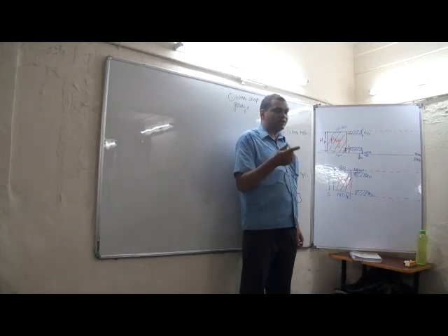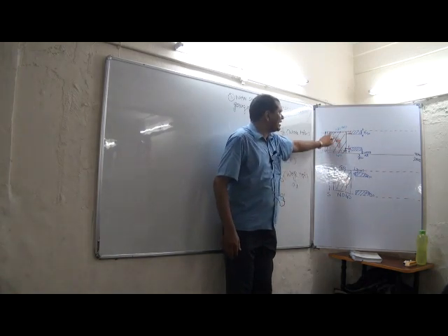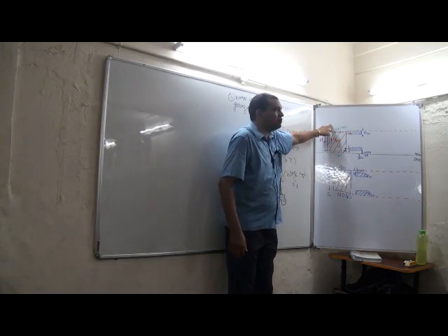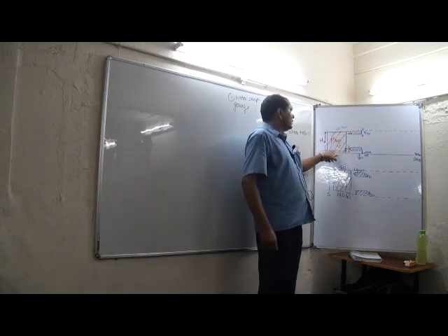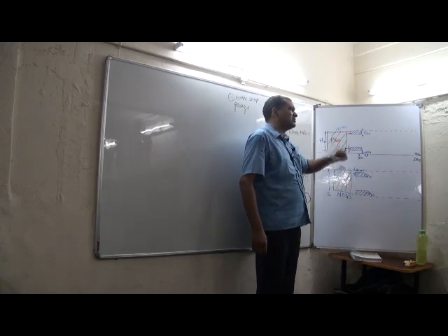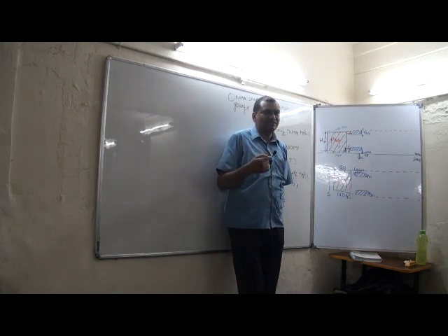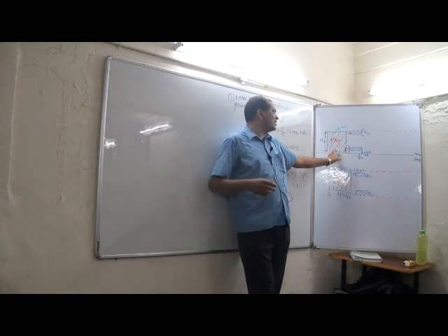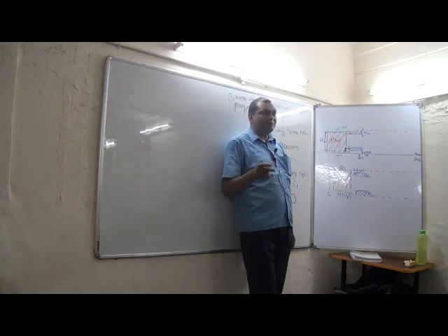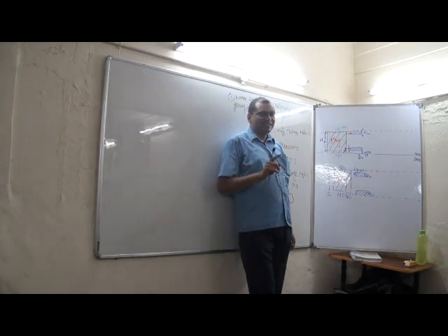By adopting the workshop gauges, although we are not accepting any hole beyond the tolerance, some of the good parts will be treated as bad parts. By accepting the workshop gauges, these good parts will be treated as bad parts. That is why it's an evil. Gauge tolerance is a necessary evil.